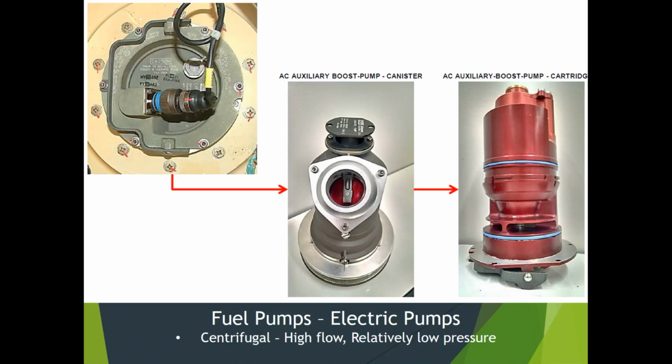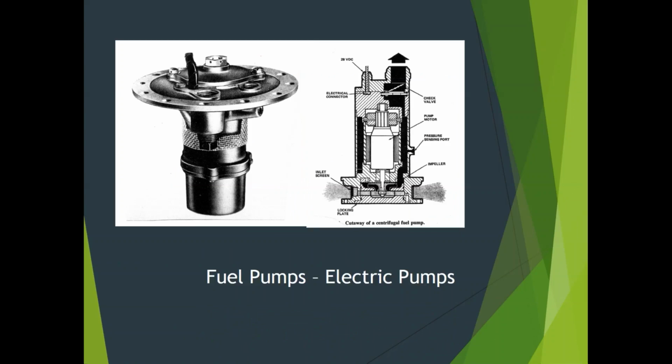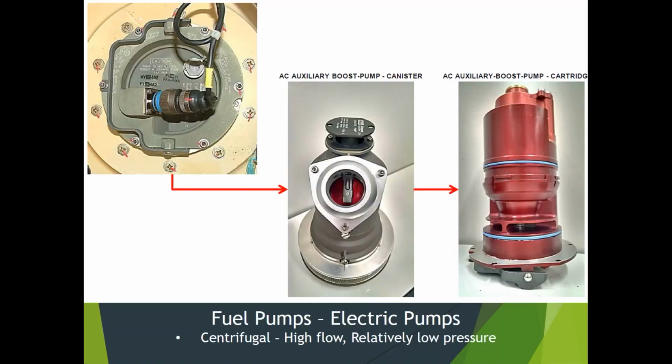And that's the other thing: with older pumps like this, you can see the fuel tube and the power. On this one, it's on the outside. This one here, it's on the inside. They used to run power to these things through the inside of the fuel tank. Now, these wires would often be encased inside of metal tubing and all that, but still, if things aren't done carefully, it can turn into a TWA Flight 800 where you have a fuel tank that ignites. So newer planes, the electrical is all external now.